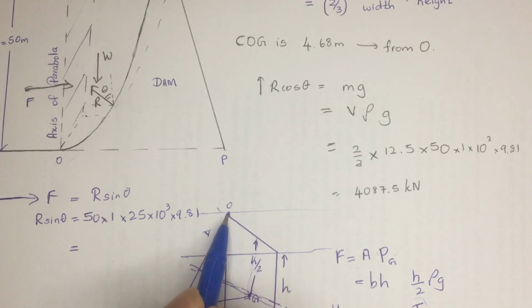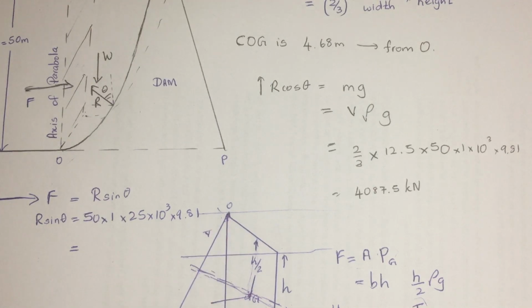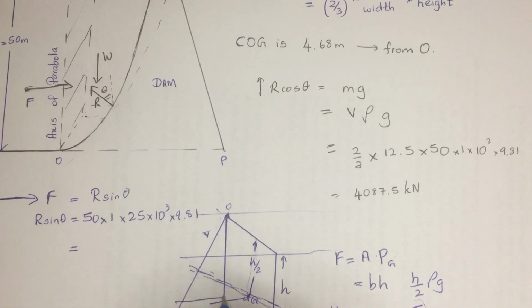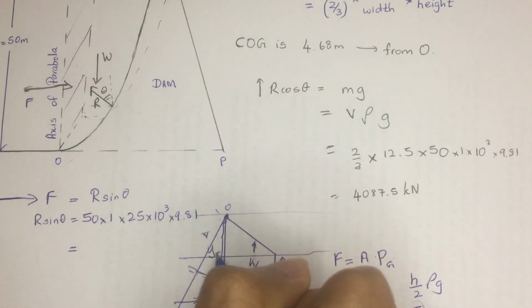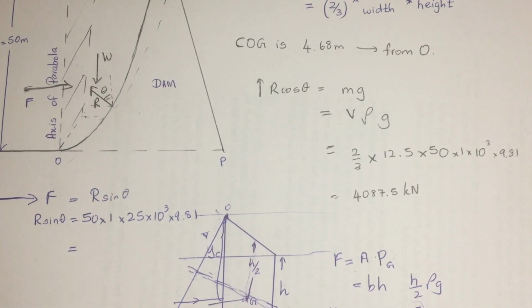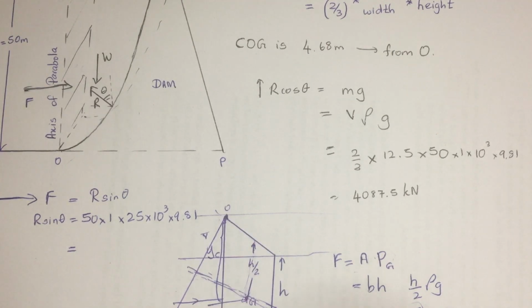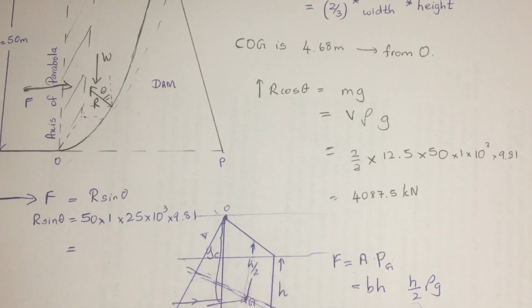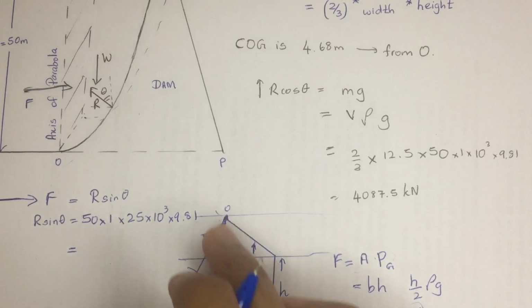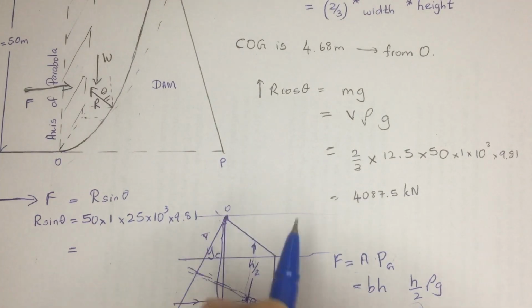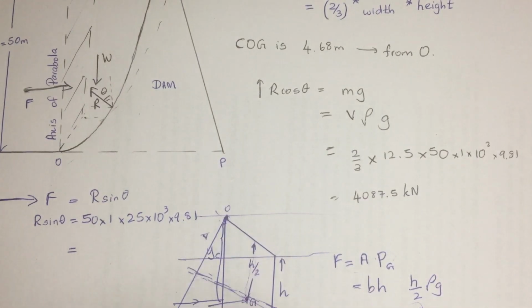Actually we knew that there's a force that is 0 at the top, and another force that is very big, and we are going to find the resultant force. We know its magnitude. We are going to find the depth at which it acts, let's say YC. But if you have a rectangular area, you don't need to remember that. When you have any other areas, you need to use this equation. But if there is a rectangular area that starts from the free surface, you can directly use one equation.